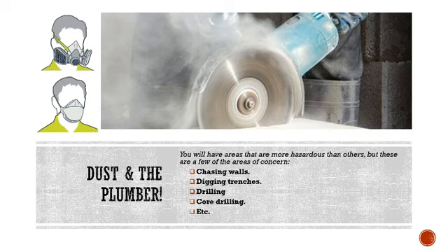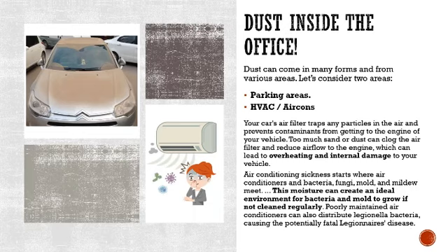So the risk assessor really must be on the ball to know what task you are performing, the time frame, what is being chased, and what material is being cut or dug into. Even when it comes to drilling or core drilling, all of that information needs to be set out in a safe working procedure so that the risk assessment can be documented properly, and the individual performing the work can then be protected with the correct type of safe working procedure on the risk assessment side, the PPE side, as well as the proper training on what to do.